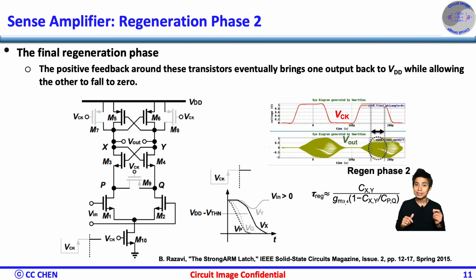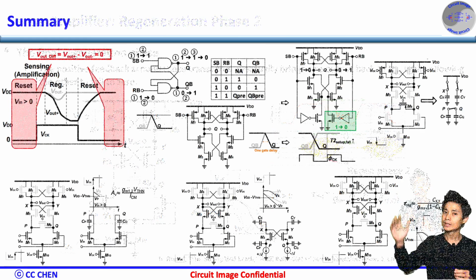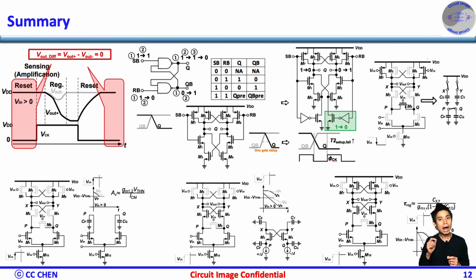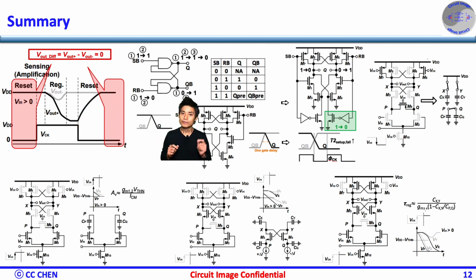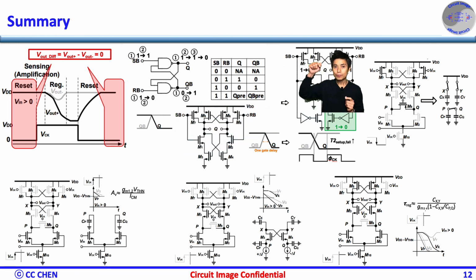The rest of the design work is to size properly in your design process. Here is a summarized image of why the StrongARM latch needs an optimized SR latch to meet the digital timing and the block interface. First, during the StrongARM's reset phase, the outputs are not valid data and must be converted through the SR latch. But the SR latch's falling transition must follow the rising transition, which adds extra unnecessary delay. With a simple pull-down device and the right polarity, both rising and falling transitions will match properly and shorten the gate delay. This is a soft reminder that the sampler's clock to Q delay is not just the StrongARM delay, but also the SR latch delay. Therefore, the improved SR latch does help a lot to speed up the timing margin.